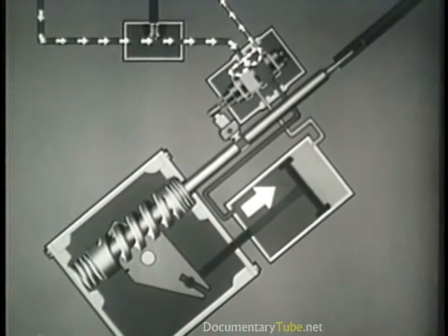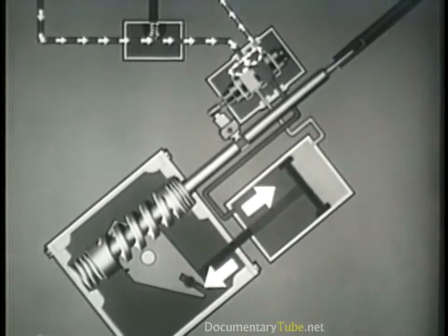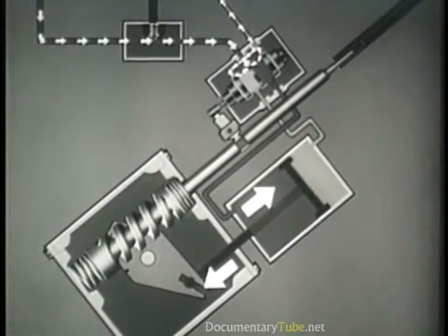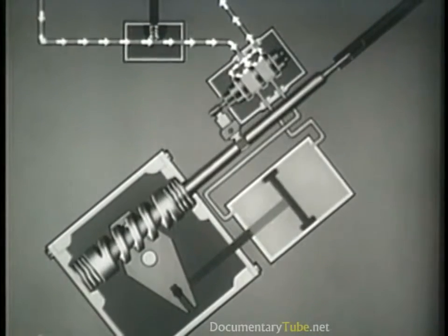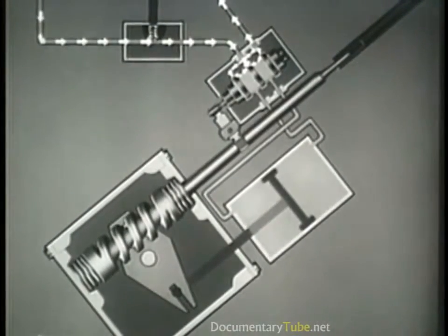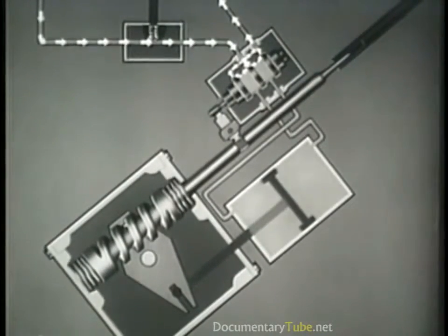This also moves the control valve linkage and positions a valve spool where fluid pressure will equalize the force exerted by the steering geometry acting on the piston rod. The front wheels can then be held in any desired degree of turn. On return to neutral, all fluid from the pump is directed back to the reservoir. The pressure is lowered throughout the hydraulic system, and the piston and piston rod do not function.